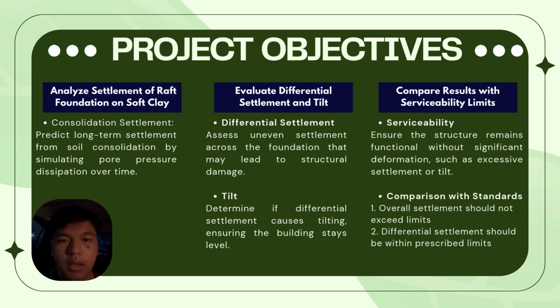So moving on to the project objective, our main goal is to understand how a rough foundation behaves on soft clay. Firstly, we will study the settlement of the rough foundation on soft clay. We will estimate the long-term settlement caused by soil consolidation by simulating how pore water pressure decreases over time. This helps us understand how the foundation settles gradually and how it affects the structure.